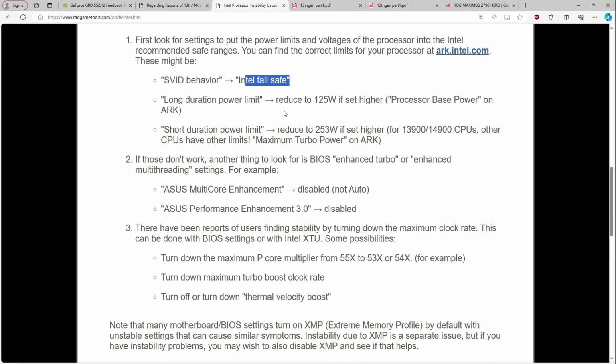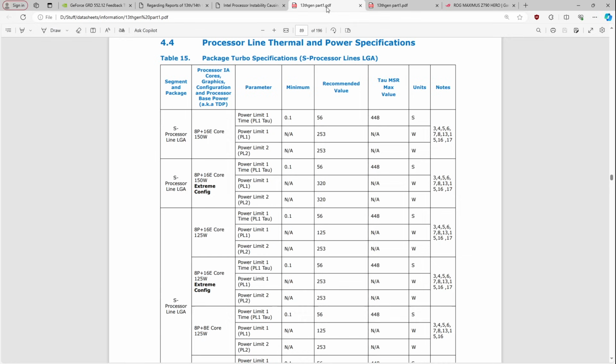Actually, one thing you could also try, if you don't want to mess with the power limits or the operating voltages, is to set a lower thermal limit. If you set the thermal limit to 85 degrees, the CPU will clock itself lower, because it's going to hit 85 degrees long before it hits the actual thermal limit. It's just going to end up clocking the CPU lower to stay below 85 degrees Celsius. But that would also fix the instability, right? Because at lower operating temperatures and lower frequencies, you need less voltage to maintain stability. So that would work. We've covered all of that, I think.